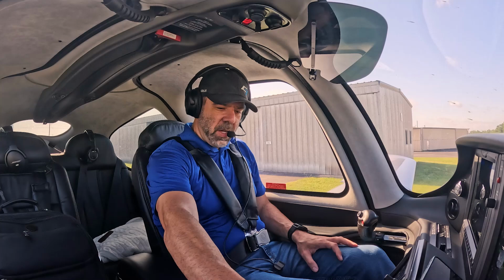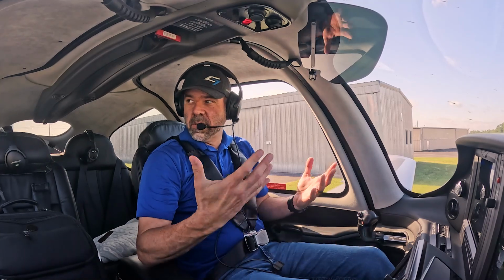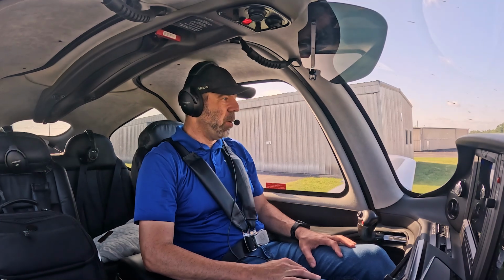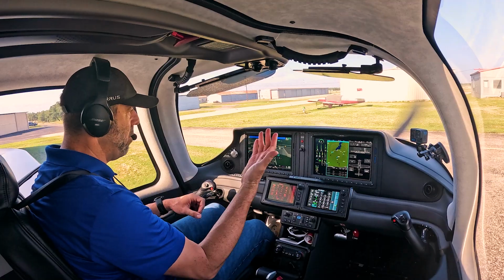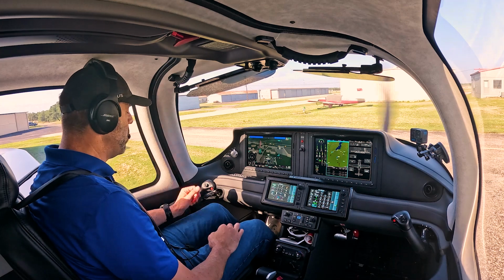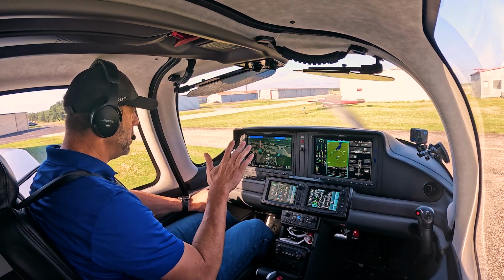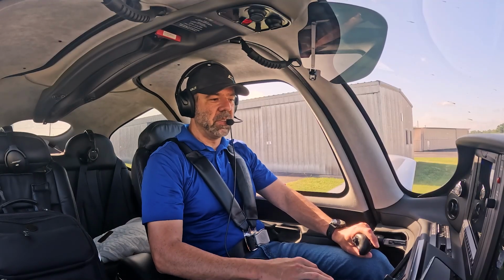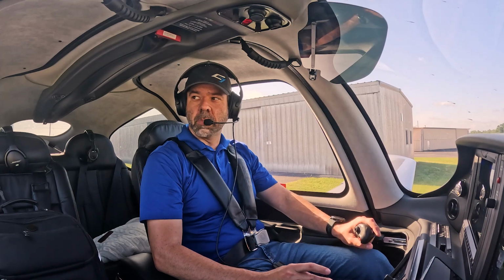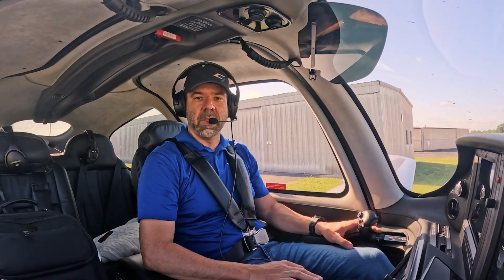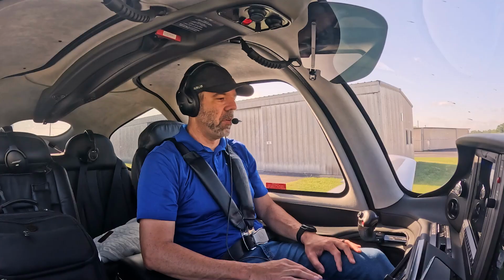All right, guys, so we've got information Whiskey. The wind is what it was when I checked it about an hour and a half ago. So we're departing 18. We're going to have a crosswind from the right. So we're going to do full aileron deflection into the wind as soon as we take off. And as those control surfaces become more effective with speed, we're going to slowly release that pressure and stay on that center line with our rudder pedals, using that left rudder.